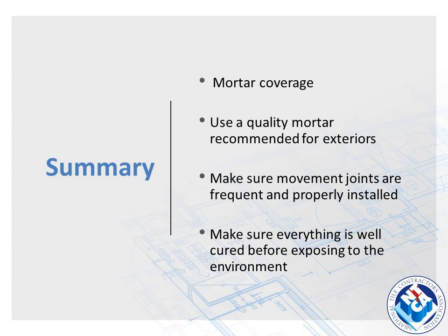Make sure movement joints are frequent and properly installed, every 8 to 12 feet in the full depth. Make sure that everything is well cured, a minimum of 72 hours after installation in 70-some degree temperatures before exposing it to the environment.